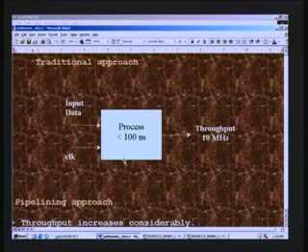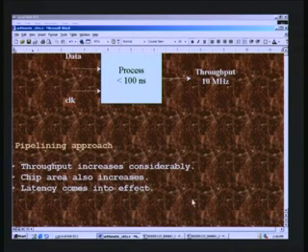So if a multiplier takes this much time, we can't do anything worthwhile as far as real time processing is concerned. So what we do is we adopt what is called the pipeline approach, and this approach basically has advantages as well as disadvantages. The advantage is that the throughput increases dramatically, and let us say for instance you have only 10 megahertz throughput. So how about jacking it up tenfold? Is there any trick we can play so that this throughput increases tenfold?